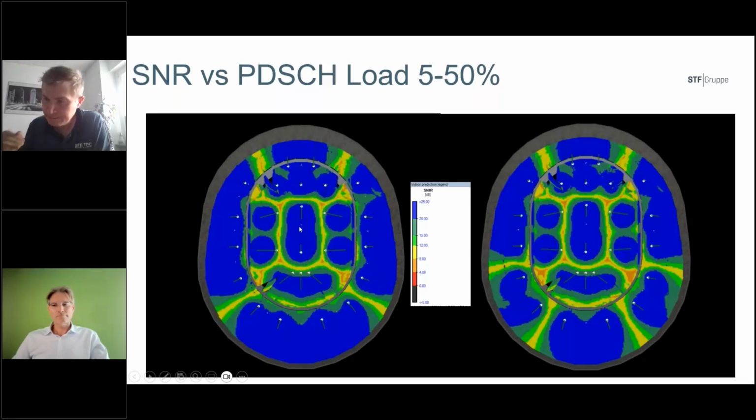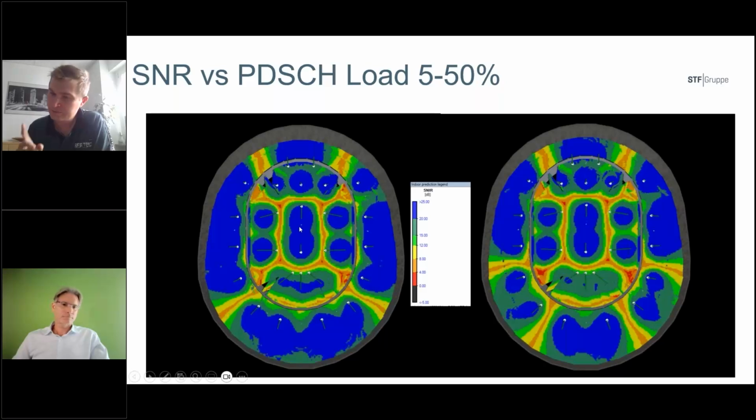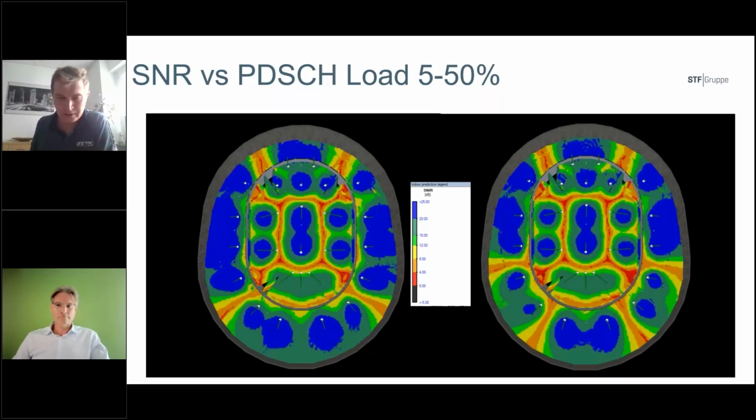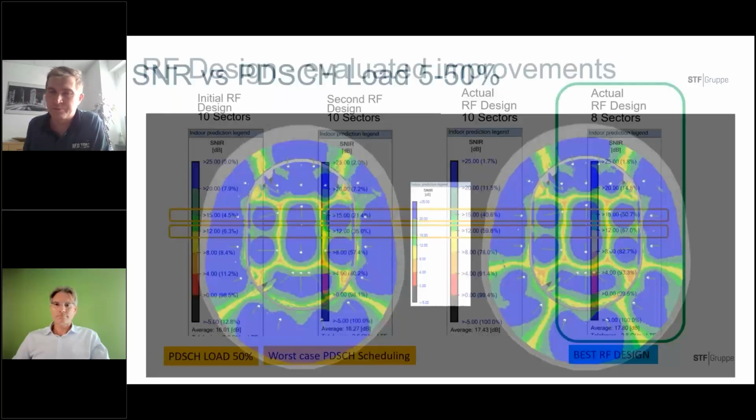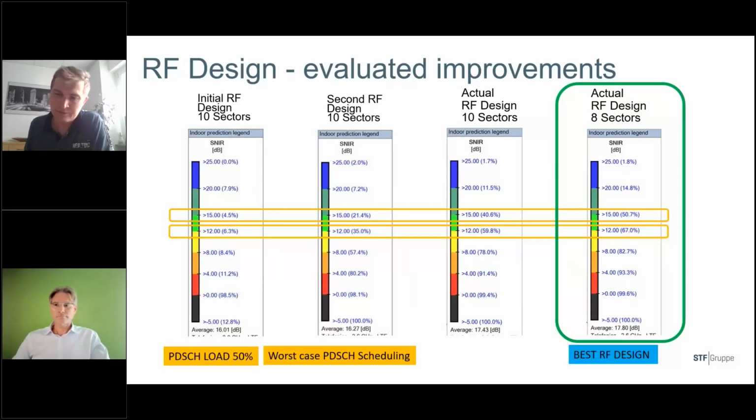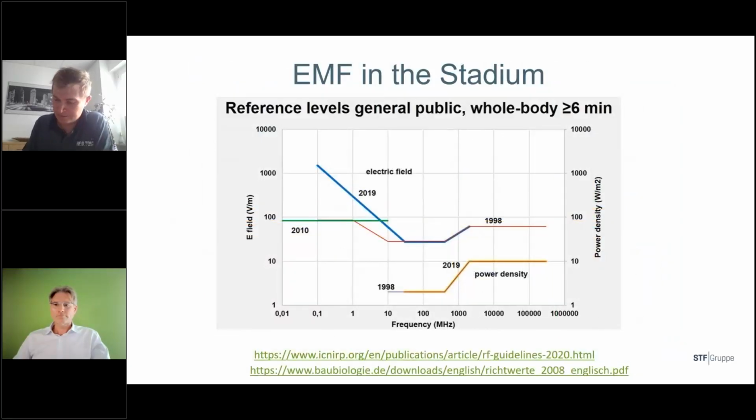And this is again a repeating story. Sometimes architecture limits you from having more cells, even if you have calculated it through, let's say, the XLS calculator. And I find it pretty interesting in IBWave that there is the opportunity to combine traffic profile setting and SNR calculation. It gives you an advantage that a typical calculation in XLS cannot give.